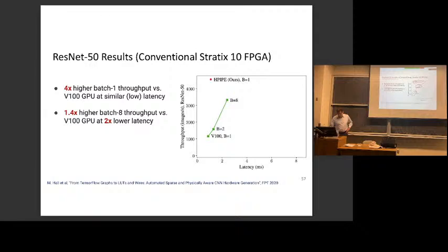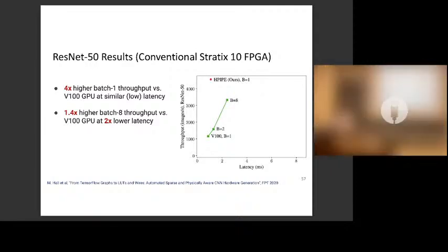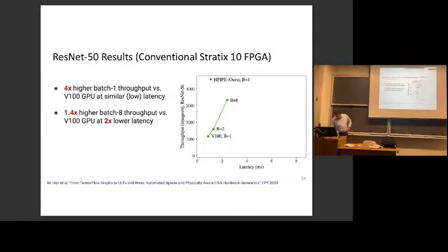Its latency's gone from 1 millisecond to 2 milliseconds. Does that make sense? Now if you keep extending this curve up to a high enough batch, it eventually does, at some higher latency targets, exceed the throughput of the FPGA accelerator. So FPGAs really like low latency. It's one of their strengths.